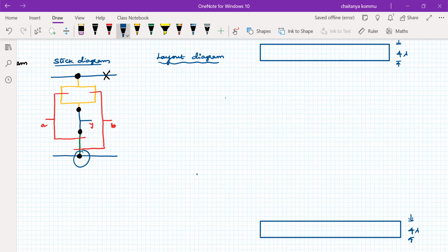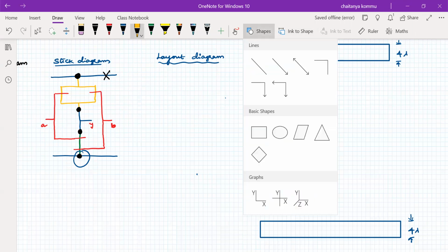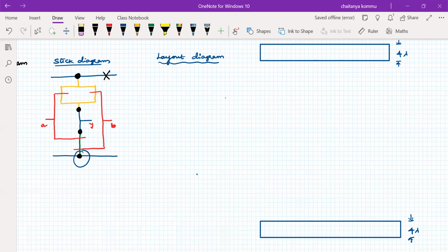Now the diffusion lines are required according to the notations there. So yellow diffusions are required. So how can I do this? This is the one diffusion. It's 2 lambda by 2 lambda thickness. I need a square box, so for the square box again I have to do this. This is also connected at this point closely.